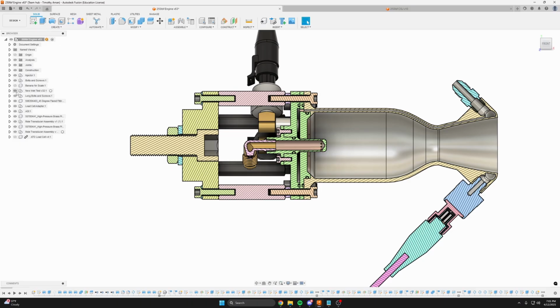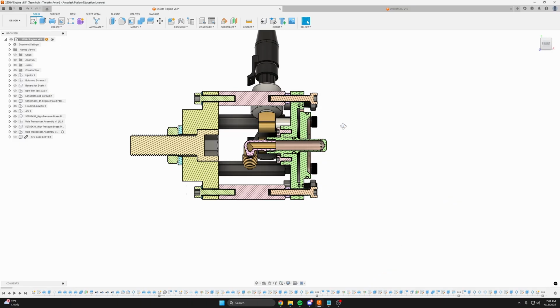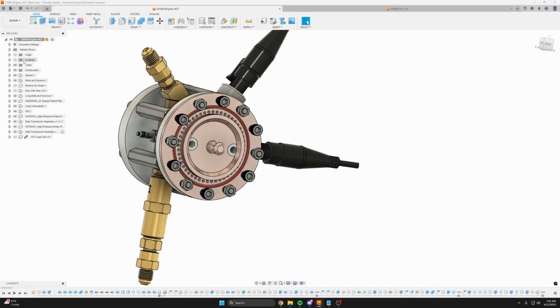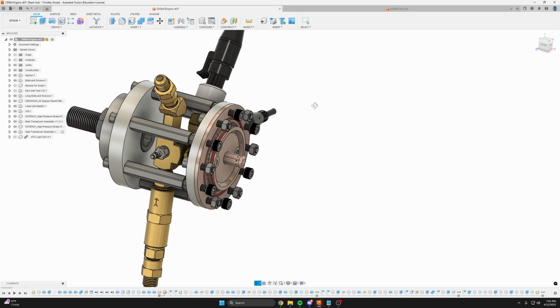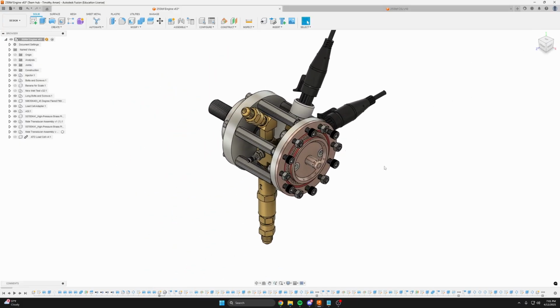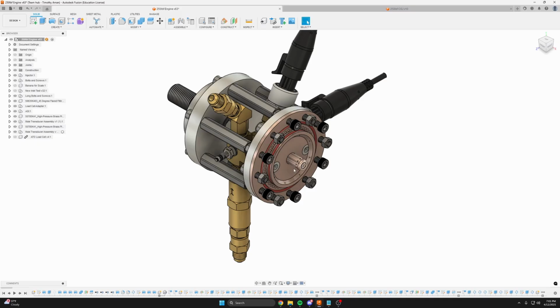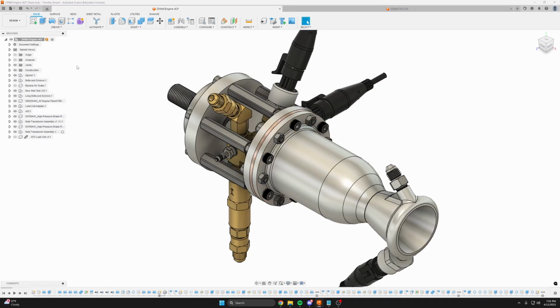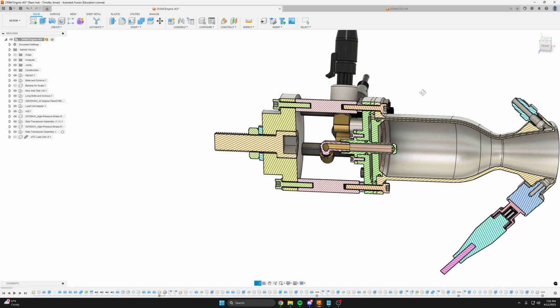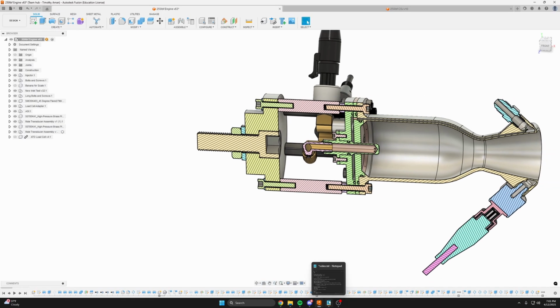You can design it such that this injector can accept any chamber, whether it's a heatsink chamber or the regeneratively cooled chamber. Some people call it a battleship chamber or battleship nozzle, to just fire for a few seconds, qualify your injector while you work on the main regen cooled chamber or what have you.